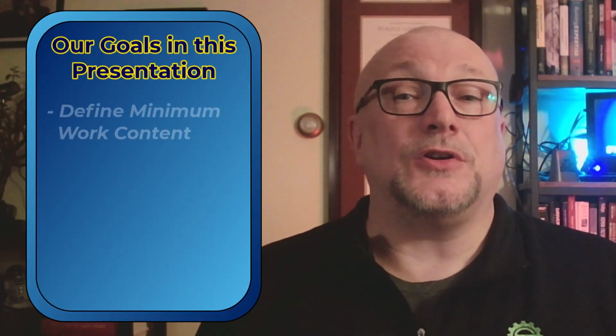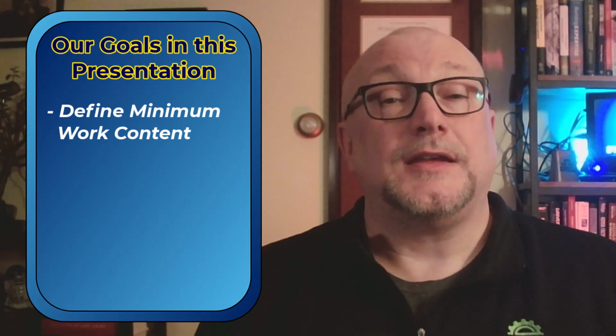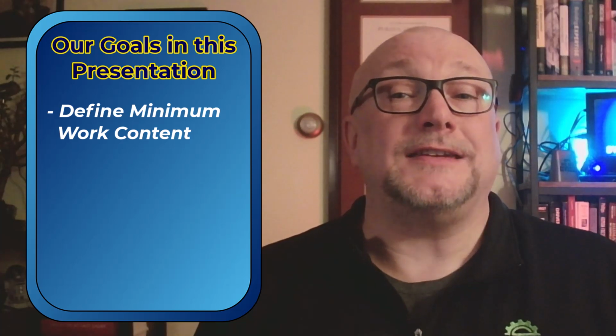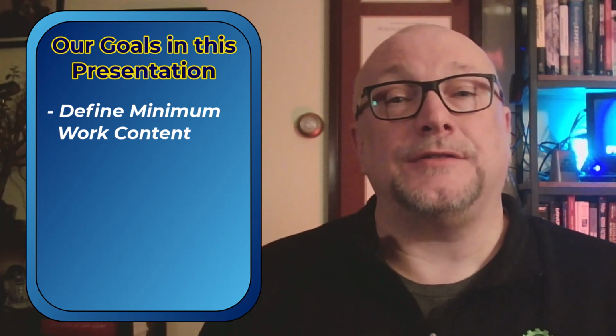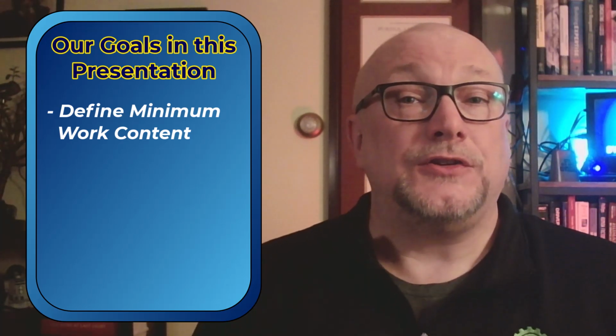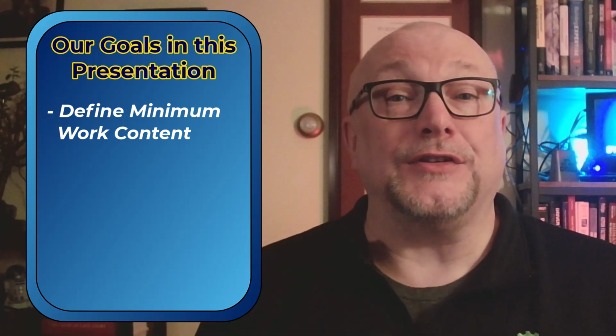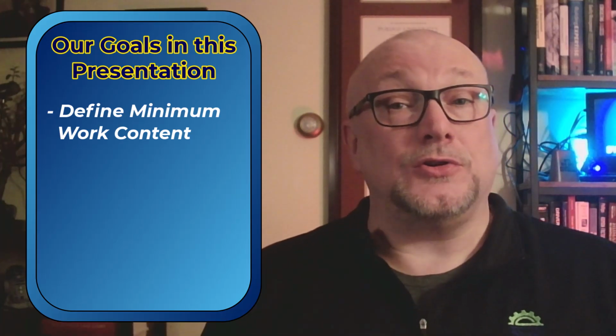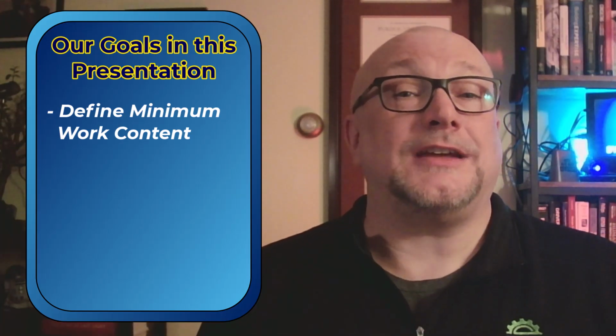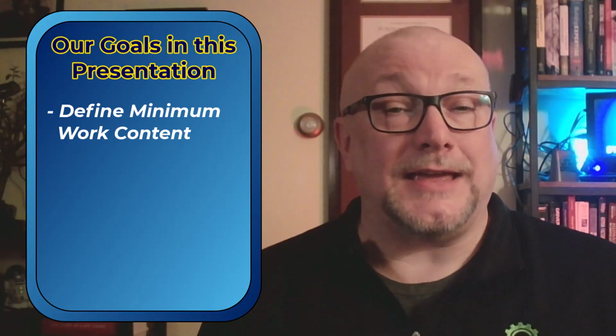In this video, we're going to examine production time and how waste expands it. At the center of this discussion is something called minimum work content. By definition, minimum work content is the absolute least amount of value-added work required to deliver a product or service. And that is the goal. But in most systems, production time extends well beyond that minimum.